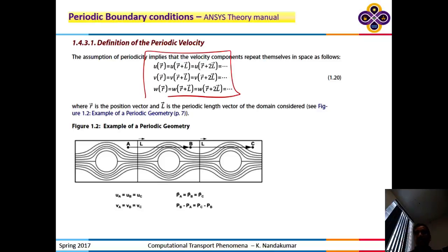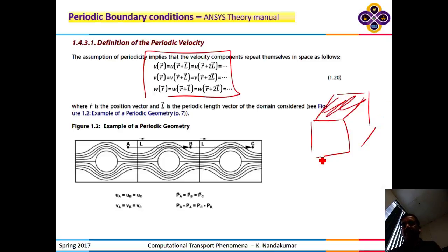And they do that by taking a box that is periodic in all three dimensions, meaning what happens in the top is the same as what happens in the bottom, what happens in the front is the same as what happens in the back, etc. And they use very sophisticated methods of solving the Navier-Stokes equation, not COMSOL type finite element method, but so-called spectral methods, where they take Fourier series, expand the solution in terms of Fourier terms.